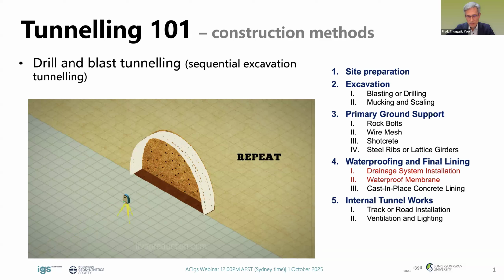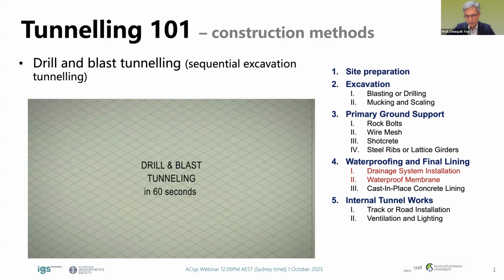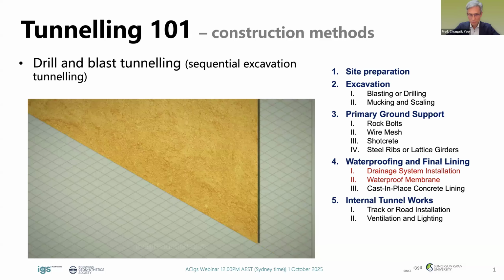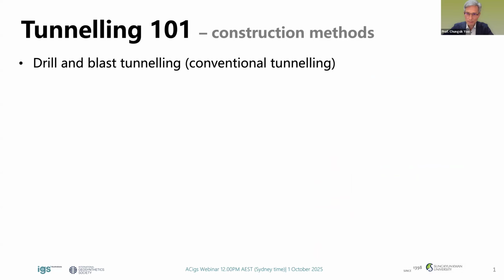And sometimes you install rock bolts as well. And this is the one cycle. So you repeat this over and over again until full excavation is completed. So here the geosynthetics play an important role as waterproofing and drainage layers behind the tunnel lining. Okay. So this is a recap.